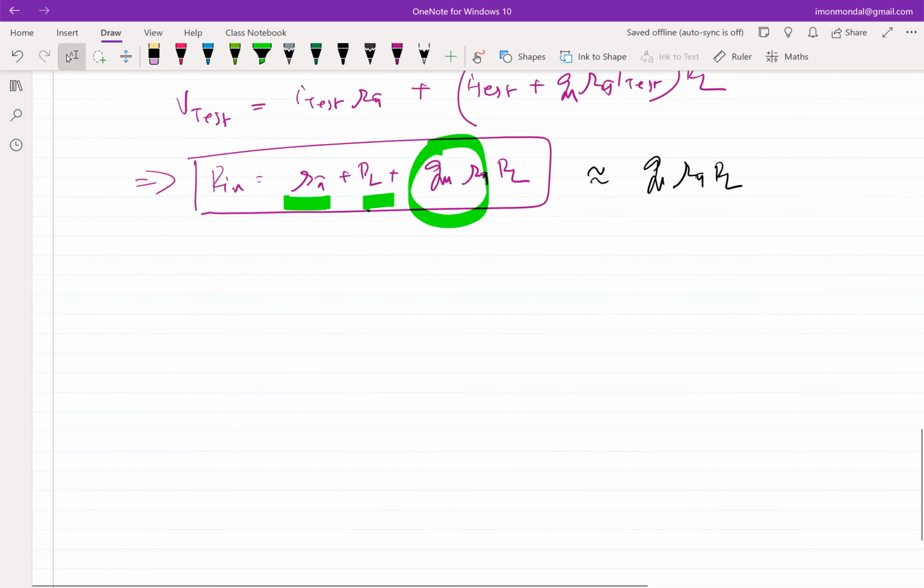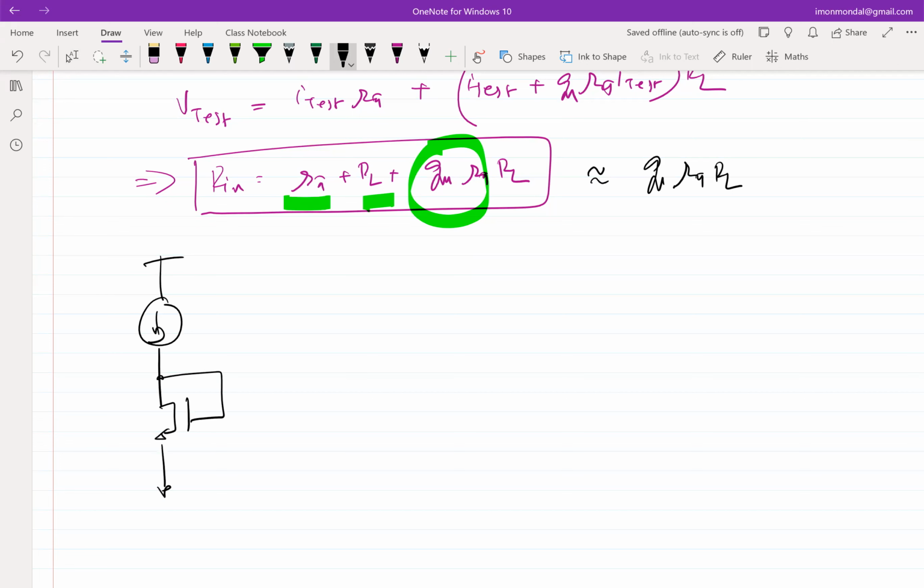So essentially, everything that we have done with MOSFETs is possible with BJTs. I'm only pointing out the critical differences that you need to take care of. One critical difference that appears because of this base current is the effect on current mirrors. So in case of a MOSFET, you had this structure, you have something connected here.